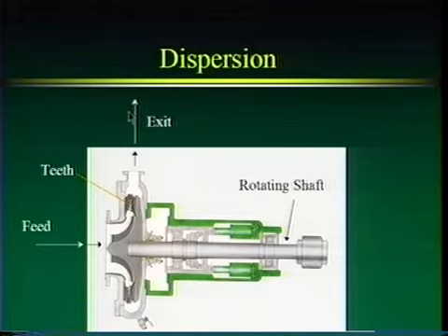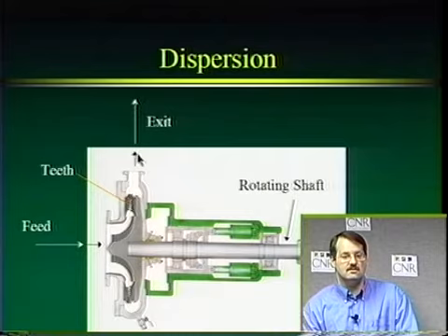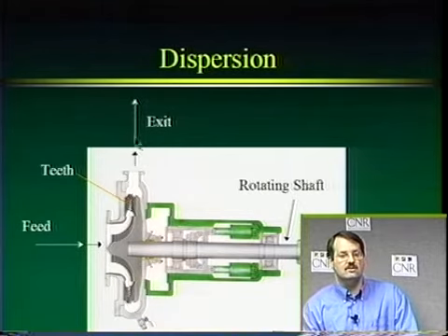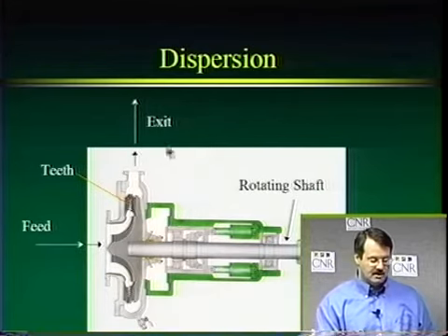So there's no rejects stream here. All the contaminants are broken up and still remain in the pulp. If we keep them there, they'll darken the pulp a little bit. If we go to a de-inking step or some type of cleaning process, screening wouldn't work very well because we've broken this up into small particles. But if we go to an operation that removes a contaminant, then we might not have that problem of darkening our pulp.